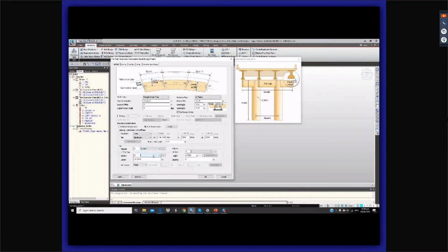Then for the material of the pier, let's input C40 for the substructure, then the section of the pier cap, the one we defined before. Then let's set the pier same with the deck. And then for the column height, set this as 9. But if you want to define different column heights for every pier, check on advanced and then modify your height here. If you input spacing, it will automatically change the arrangement of your columns accordingly. So if you put one spacing, it will input two columns. So again, here are the data for the layout tab.